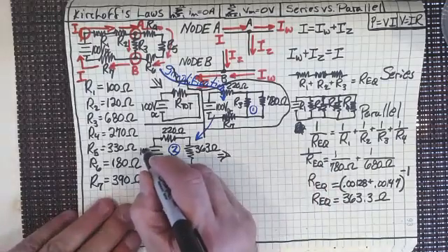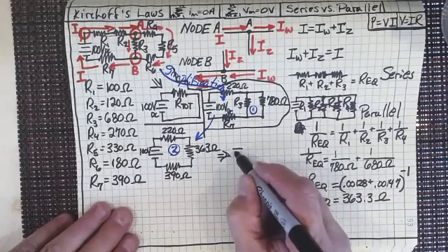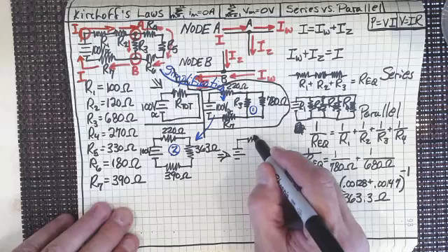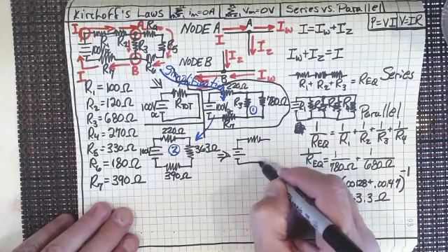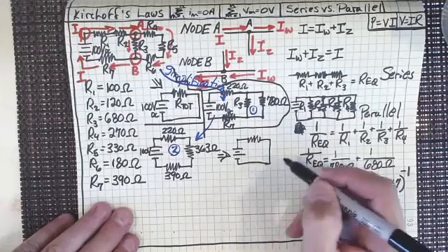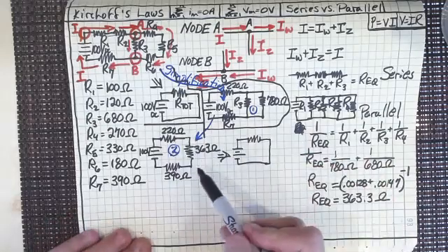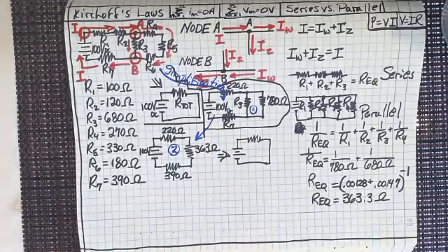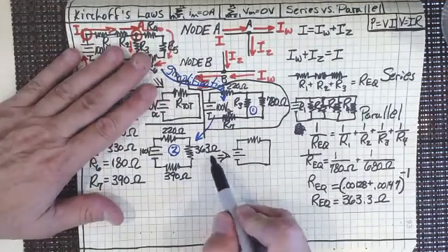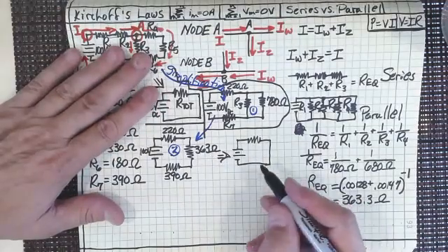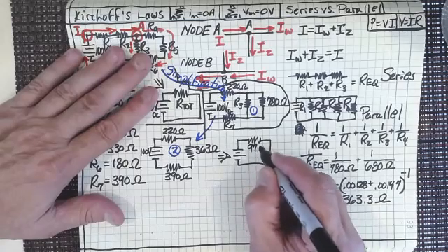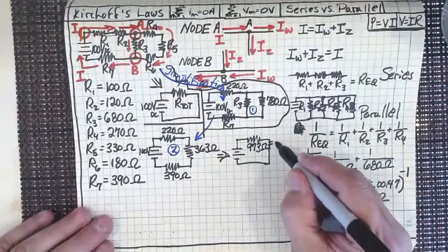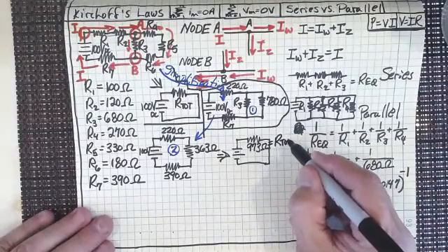Well, let's not forget our 100 volts DC. So let's draw our last circuit, and that's with the 1 resistor, isn't it? And that's going to be our total resistance. And so 220 and 363, actually, why don't we do 220 and 390? That gives me 610. 610 and 363 gives me 973. 973 ohms. That's the total or equivalent resistance of that circuit.